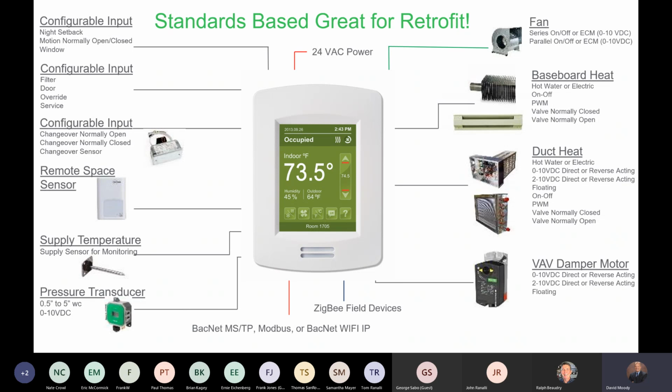Now, this is an important thing to understand about this device. You can use any pressure transducer that you like with it that has a range of 1/2 inch to 5 inches. It's configurable. You just tell it, hey, I'm either 1/2 inch, and it works in 1/2 inch increments, 1 inch, 1.5 inch, all the way up to 5 inches. You can use anything that you like as long as it's 0 to 10 volts. It will not work with anything other than a 0 to 10 volt pressure transducer. And in our kit here, in the bundled kit, this is the transducer you get.